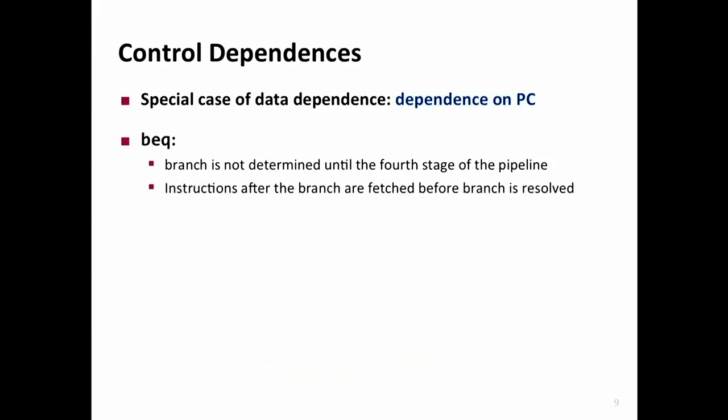One obvious, very simple prediction mechanism, as we discussed yesterday, is predicting that the branch will not be taken. Basically, the branch will not jump to the target address. It will fall through to the next sequential instruction. This is called a fall through. A taken branch goes to the target address, a not taken branch falls through to the next sequential instruction. So if you assume that the branch will not be taken, you keep the pipeline full with the instructions in the sequential instruction stream.